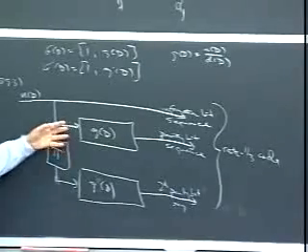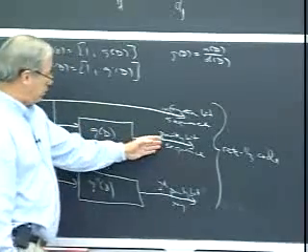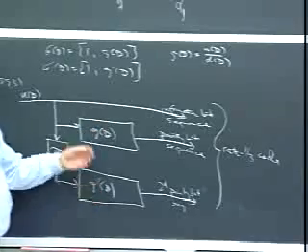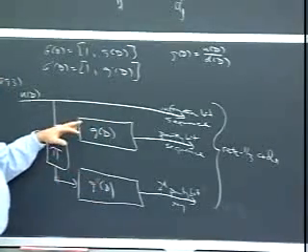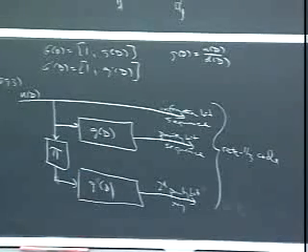The basic idea is you don't want an information sequence which gives you a short code word out of here and a short code word out of here. And making it recursive, having feedback, is what you need to do to prevent that. It also gives you better codes, but I don't think that's really why.